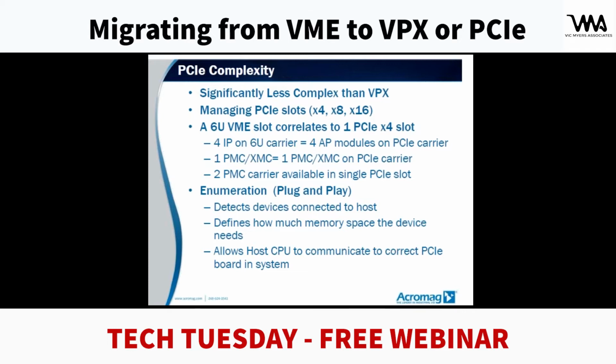PCI Express server complexity, it's much less complex than VPX. A couple of the things that need to be looked at and managed are, on your motherboard, you have only so many what we call PCI Express connections lanes. So you need to manage how many slots in your chassis, what type of boards you're going to be using, and what type of interfaces they have on them.